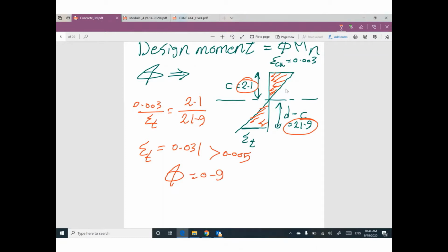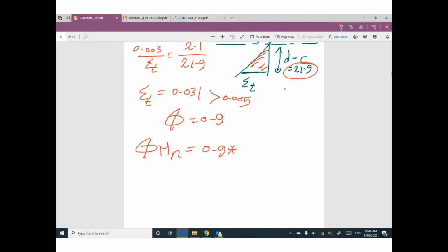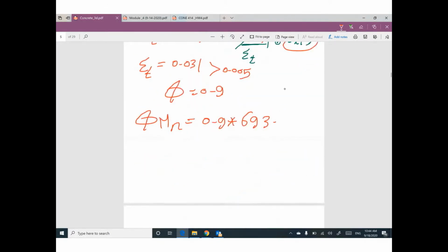Your design moment, phi Mn, will be 0.9 times Mn, 693.6. Your final answer will be 0.9 times 693.6, which is 624.2 kip foot.